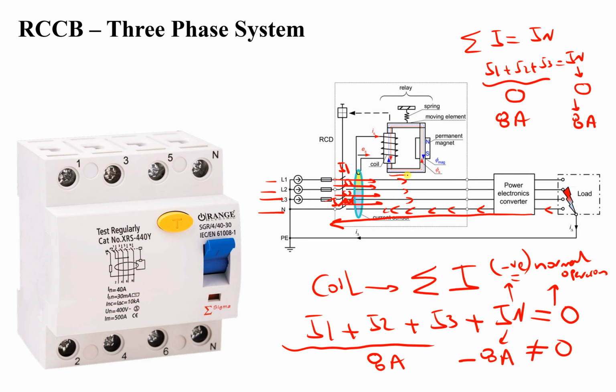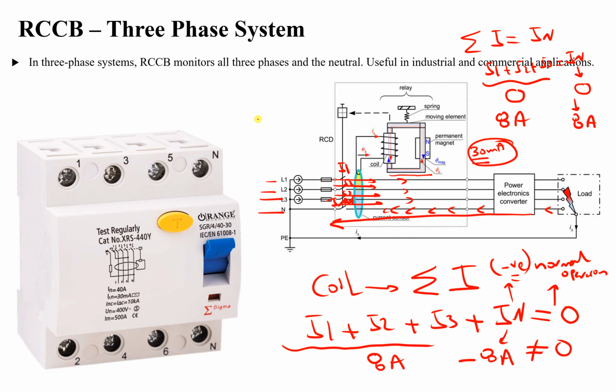Now this part specifically, the permanent magnet, why do we have this? This one is used to control the residual current value. So when we say 30 milliamperes, it is dependent on the magnetic field here and other properties. I discussed this in detail in our course for protection, so I'm not going to repeat this part in detail for now, okay? For now, let's look here.